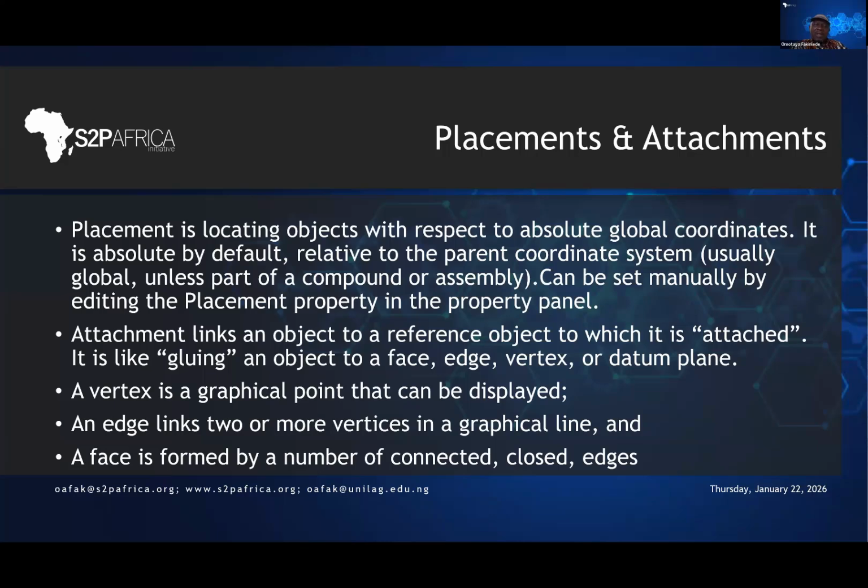It's the same thing with an edge. An edge is one or two more vertices in a graphical line. That line can be a straight line, can be a curved line. And then a face is formed by a number of connected closed edges. So a face can be a flat face, it can be a curved face. But if you are going to do a sketch on a face, that face must be flat.